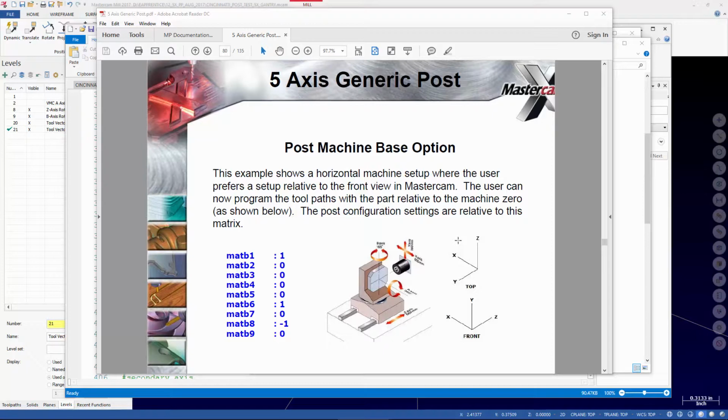Now, that said, there are certainly ways to restrict some of the parameters to only do a single axis. So for example, axis substitution is a rotary axis toolpath. There are some limitations to it inherently. So inherently, axis substitution only does a single axis of rotation, and it usually only rotates about the center.